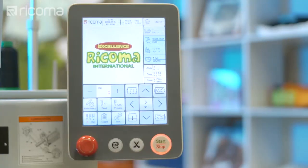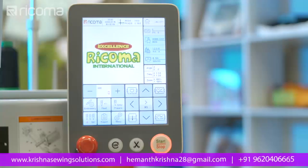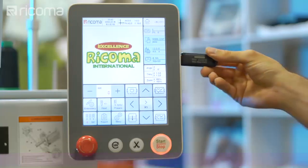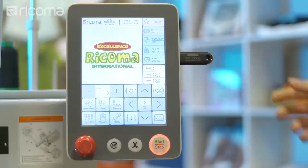In order to run an embroidery job, you must first import a DST file into the machine using a USB. Once you have your DST file saved onto your USB, insert the USB drive into the USB port on the right side of the panel.